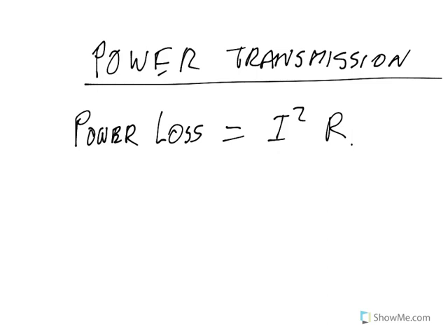So resistance, get that as low as possible. All right, so we can do that by having, because remember, one of the things is it's the length over the area. That's what the resistance is proportional to. Now the length, can't do much about that, because if you've got to get power from the power station to Melbourne, it's got to be a certain length. So we can make these wires big, but then you've got a limit. Once they get too big, they get too heavy. Reducing R, while we can do it, there's a limit to what we can do.